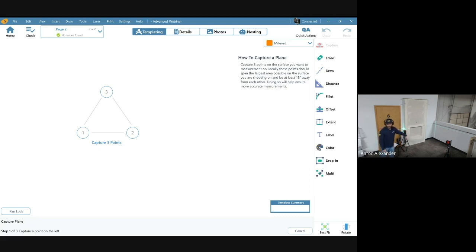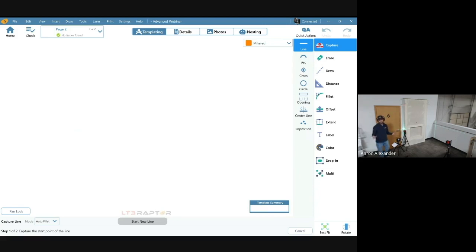So by using this laser on the floor, squaring us up to the face, which in turn is going to create us a good square edge here because we are going to install these miters square, right? So we can use this as our plane now. Okay, so I'm going to shoot lower left right onto the green laser line there. Lower right, right onto the green laser line over there. And then I'm going to come up here and shoot a point up on the wall, right on that green laser line there. Now I've established that plane.